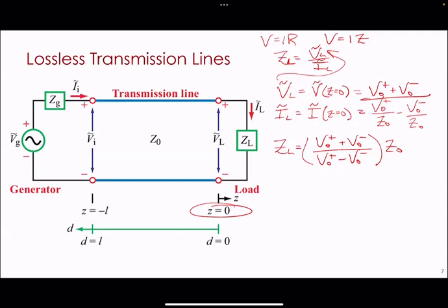And you could say, what's L prime and C prime? You go back to your equations and those just have the material properties in them, the mu's and the epsilons. That's the stuff that the transmission line is made up of. And it's got the dimensions in it. For coax, it's got the little a and the little b, which are the radii. For the 2-wire line, it's got the little d and the capital D, the diameter and the spacing between them. So basically, this one's entirely determined by the material properties and the dimensions of the transmission line. This one, if you have control of the source, you control. This one is whatever you're connecting it to.